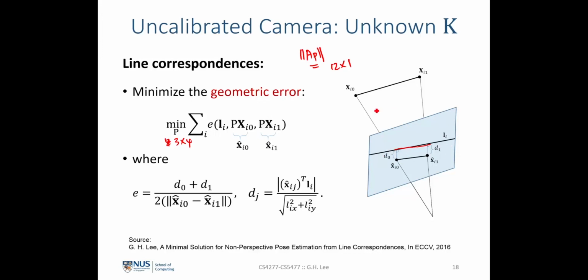But we can see that there is an inherent bias towards shorter lines. So if this line is very short, what this means is that the error that is formed by this would be smaller compared to a very, very long line. So if I have a very long line, a very small angle over here will actually make a very huge error at the two endpoints.